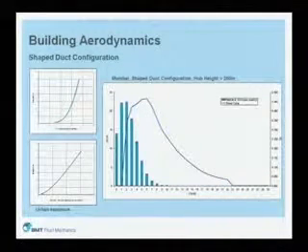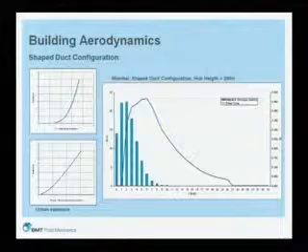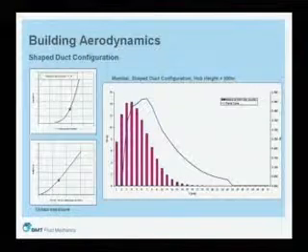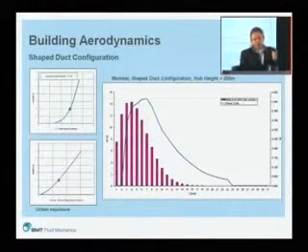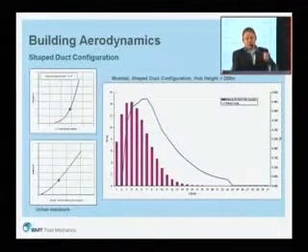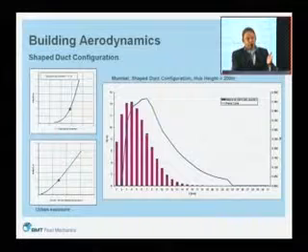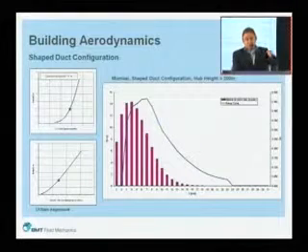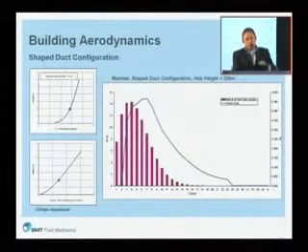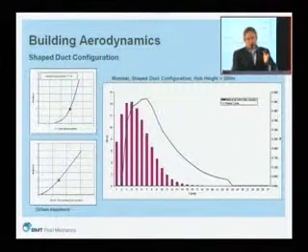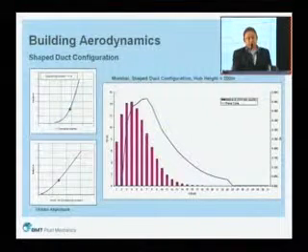So this then tells you that you have another speed up factor to apply to your basic wind data. This graph then also shows the shape of the power curve against the available wind distribution. And when you're optimizing a building integrated wind turbine arrangement, what is key is to try and get the best match between the shapes of those two curves. So you want the most frequently occurring winds to coincide roughly with the wind speed that your turbine is most efficient at.